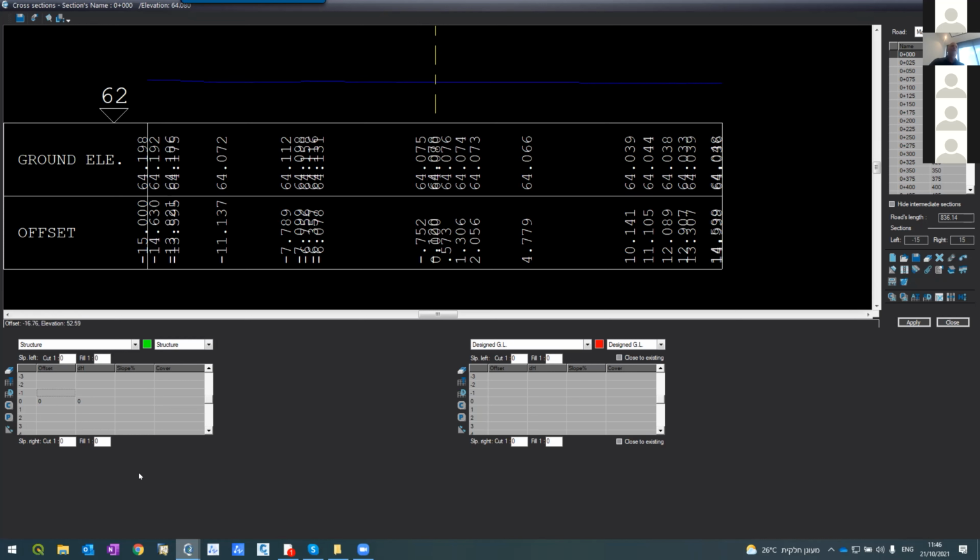And we are starting to the left. And to the left, we are going with a minus 3.65 meter lane at the minus 2.5%. So again, how do I do it? I'm starting from the center outside, always from the center outside. I'm starting with 0, 0, which is according to the vertical alignment, the crown point. And I'm starting with 3.65 meter to the left, with a slope of -2.5.